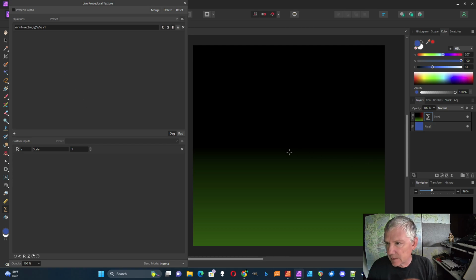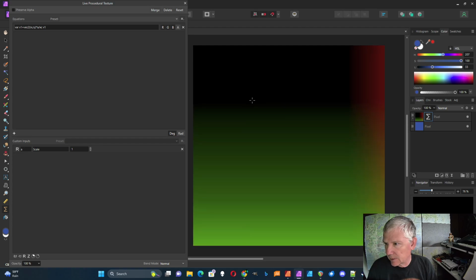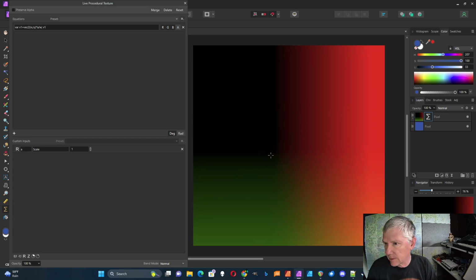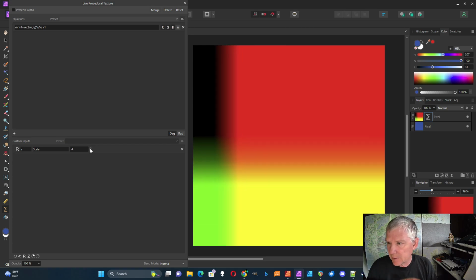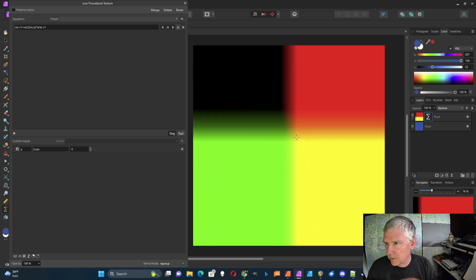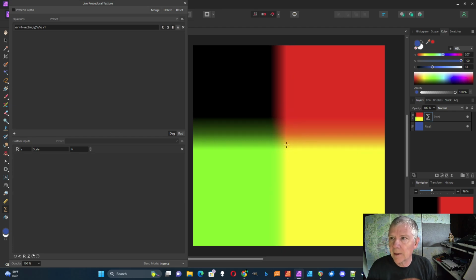Because it's relative X, relative Y. If I double click, I can drag this over to here if I want to. But I could increase the XY scaling to show it like that. I'm going to set up 4 of these. 2 of them will be for the X dimension, 2 of them will be for the Y dimension. And I want to take plus or minus 1 pixel on either side for X and for Y.